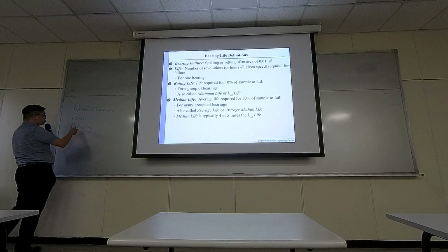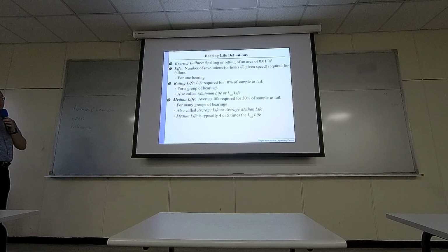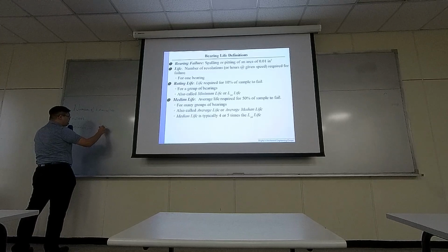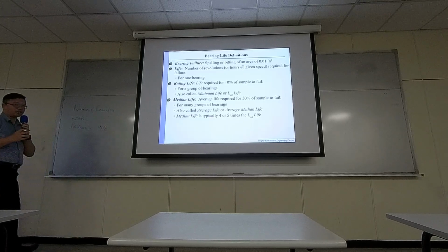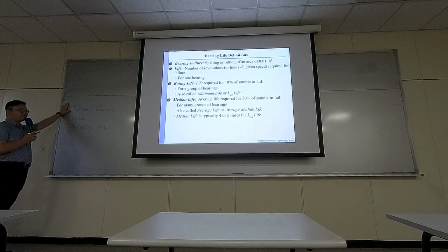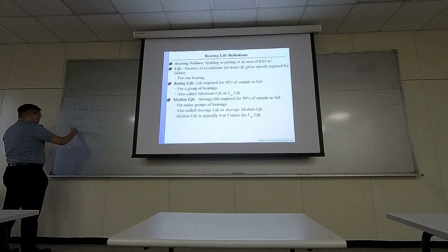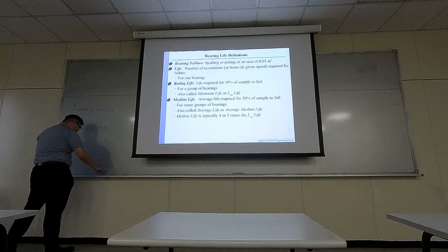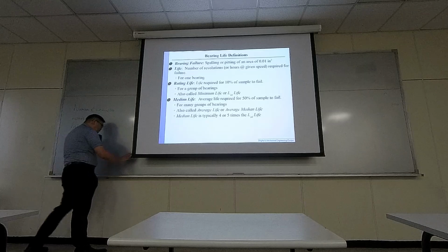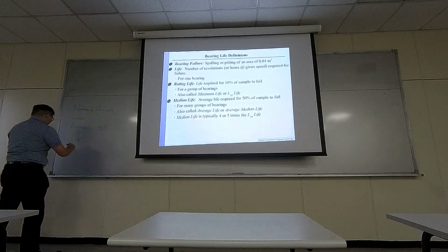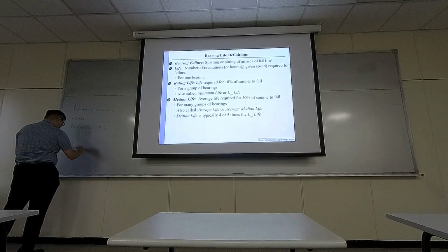So when you talk about reliability, typically for bearings, they are talking about 90%. So 90% reliable after a certain amount of revolutions while it carries a certain amount of loads. So that's why in bearing design you commonly will see a term called L10.